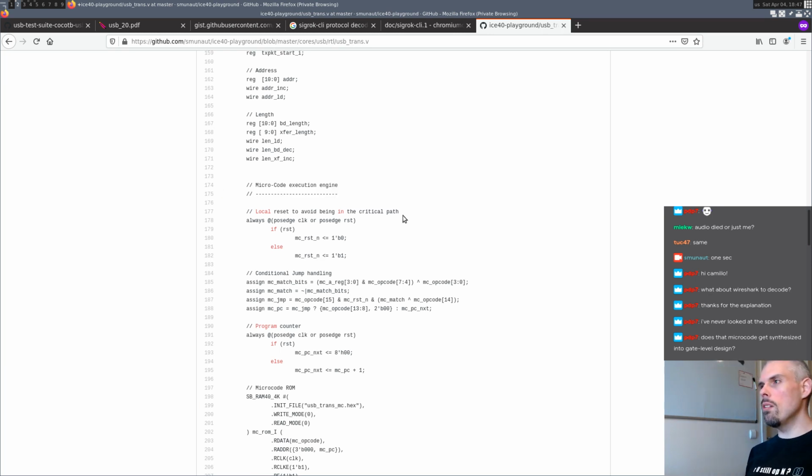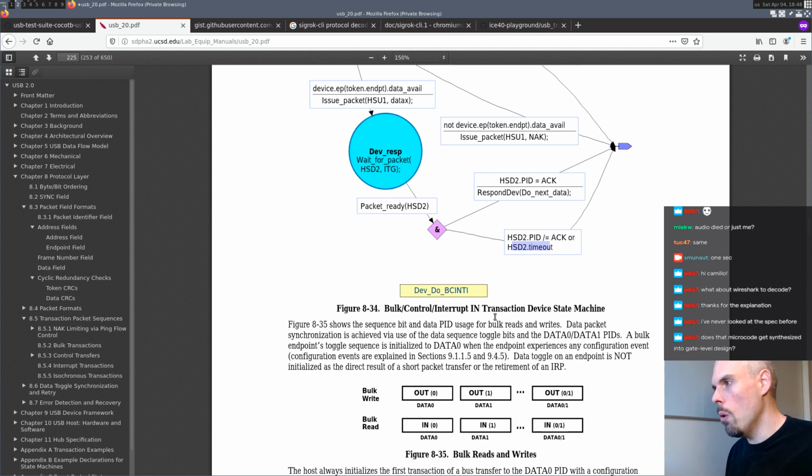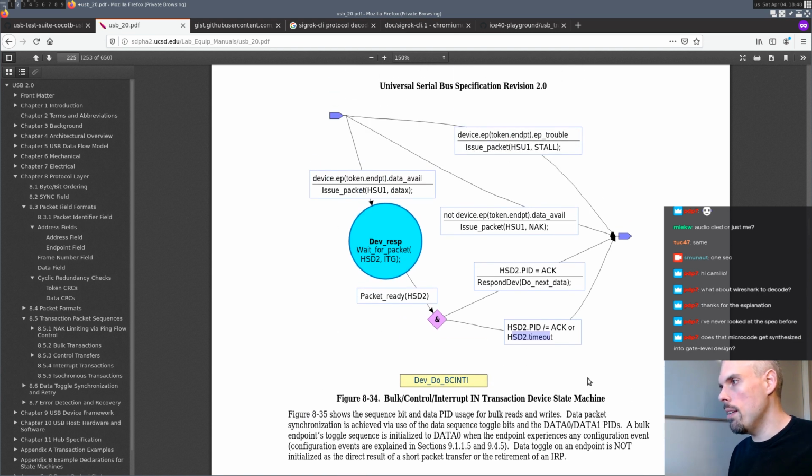The way this core is coded, you have the packet level handling, which is really the bits and the different fields inside the packet, handled entirely by gateware at the gate level, because you need very short response time, and you don't have any time to lose executing any kind of software. Then you have the transaction layer, which is those state machines, and for these you don't need to respond in one cycle.